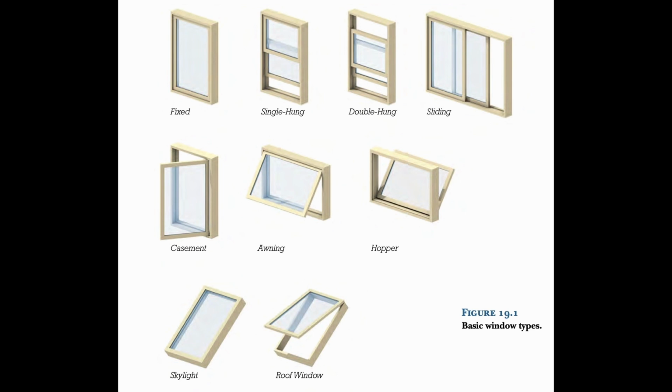Next, single hung and double hung windows have one or two moving sashes, which are the frames in which the glass is mounted. A sliding window is a single hung window on its side, pretty much. Projected windows is basically a category that oversees casement, awning, hopper, in-swinging, and pivot windows.